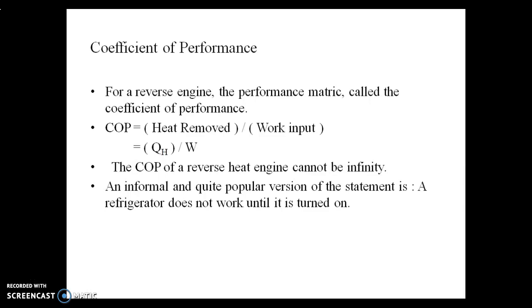The COP of a reversed heat engine cannot be infinity. That means the COP value cannot reach an infinite value. That means in this formula, the denominator cannot be 0. If you put 0, the COP value is infinity. So, in order to transfer heat from a low temperature body to a high temperature body, we must supply additional work for that heat transfer process.